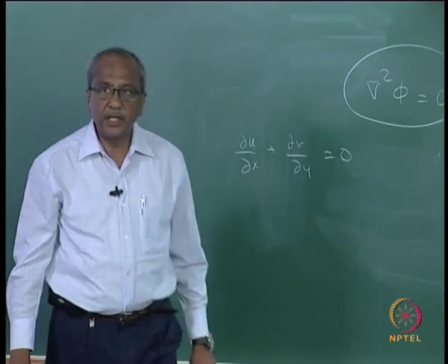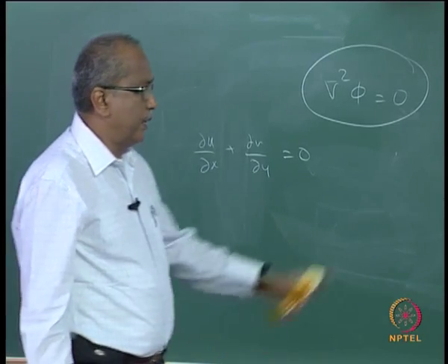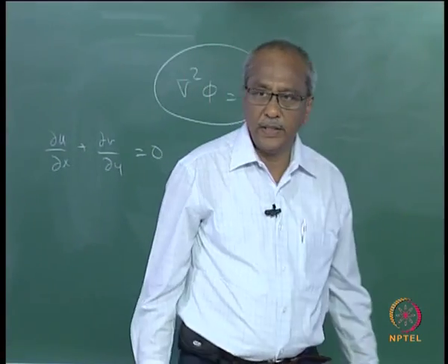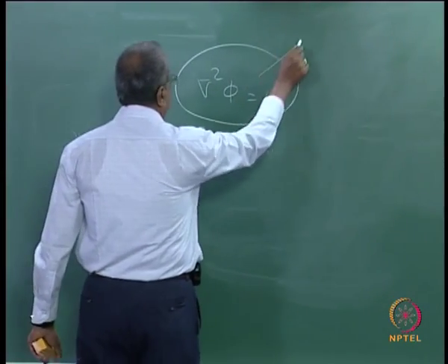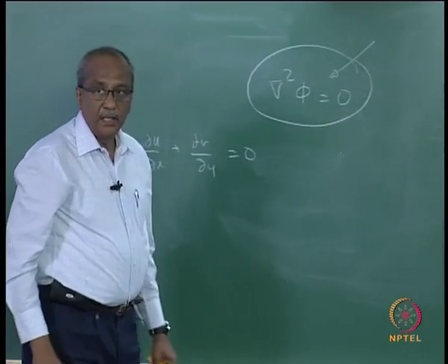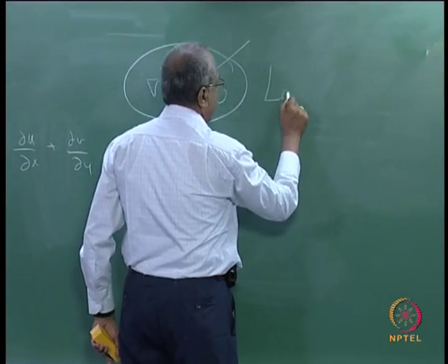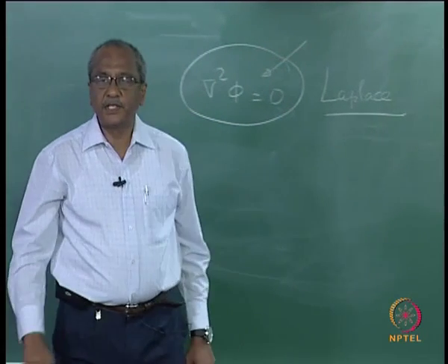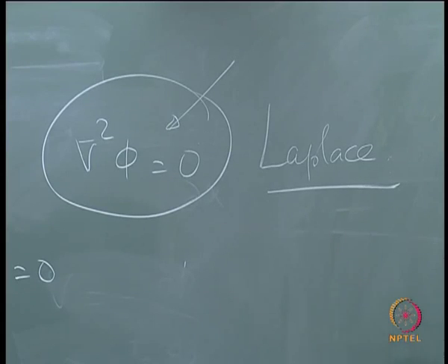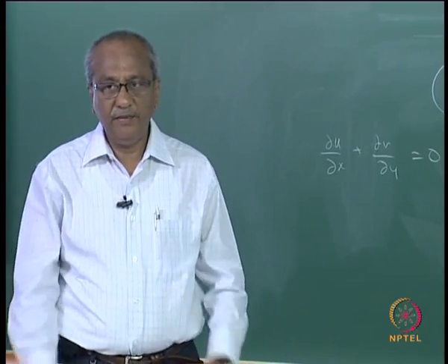So this is the equation for the continuity. Once you substitute for u and v, you are going to get the Laplace equation, and this Laplace equation will be the base, the governing equation, when you start deriving the expressions for the kinematics of an ocean wave.